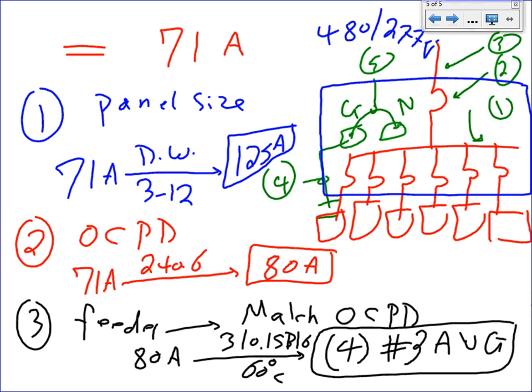You can, there's nothing wrong. We're going strictly based on the code, guys. Right now, there is no room to expand in this panel. That's where your idea comes in: I'm going to make a 125 amp panel for future expansion. But if you go from a 600 amp panel into a 1000 amp panel for future expansion, somebody will start questioning your judgment.